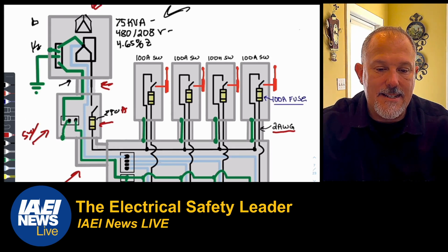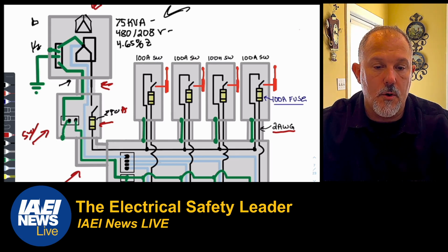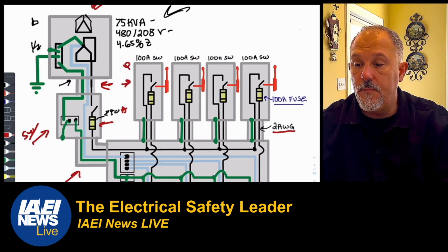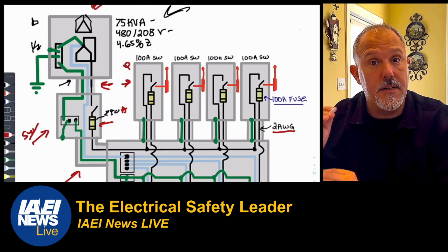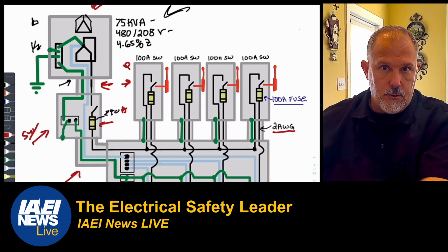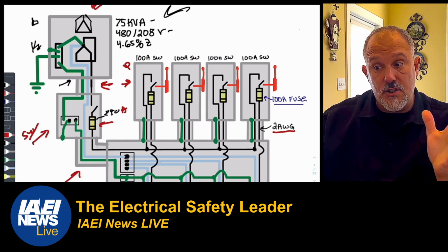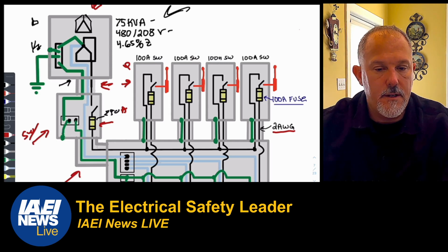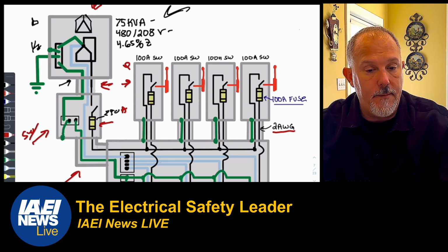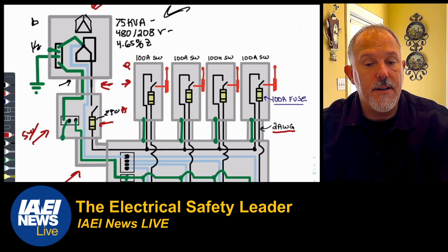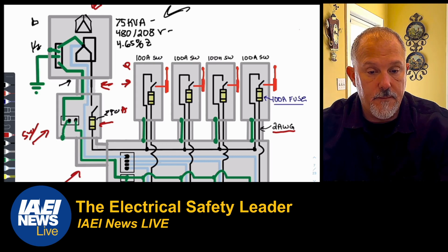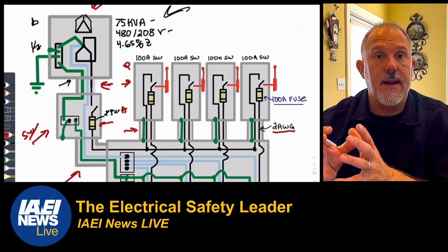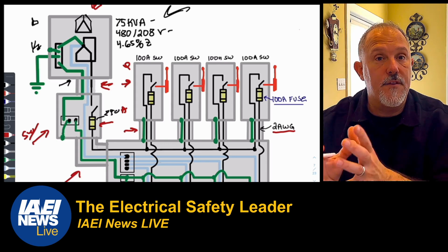The tap conductors do not extend beyond the switchboard, switchgear, panel board, disconnecting means, or control devices they supply. So all of it is contained inside of that enclosure because it lands on an overcurrent protective device. And the moment it lands on an overcurrent protective device, you're moving from a tap conductor to a feeder. So that length of conductor does not go beyond the equipment, so we're good there, except at the point of connection to the feeder, which is that device. The tap conductors are enclosed in a raceway, which extends from the tap to the enclosure of an enclosed switchboard, switchgear, panel board, or control devices, or to the back of an open switchboard. So this raceway is enclosing the tapped conductors that go into that switch enclosure, so everything is contained.